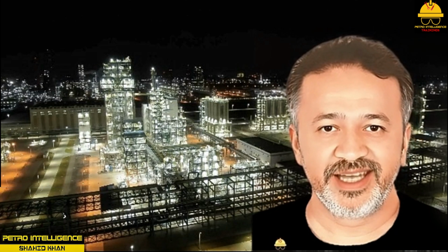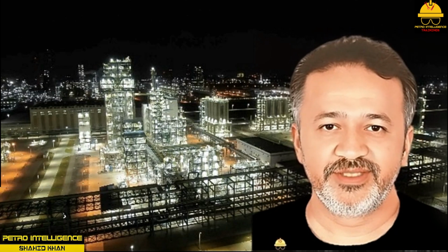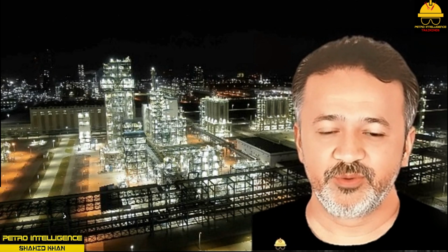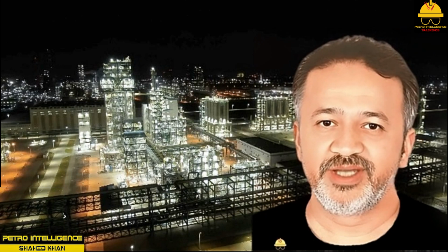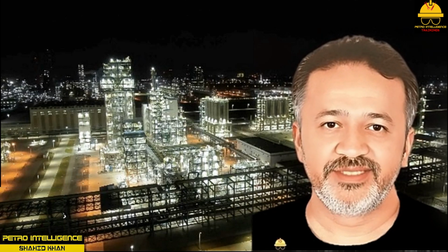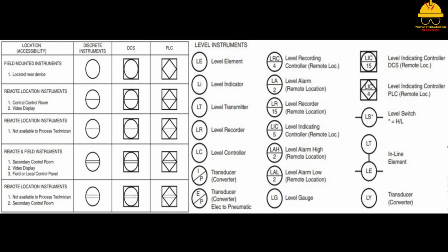As the level in a tank increases, the pressure at the bottom of the tank increases. A simple equation: H, height of liquid above the point being calculated, times 0.433 times specific gravity equals pounds per square inch. If the liquid is in an enclosed tank, things like vapor pressure or added gas pressure must be added to the total pressure. This picture illustrates the basic symbols used to illustrate level. Level indicators are very common on process drawings and are represented with an instrument symbol that looks like a circle with LI written on the inside.